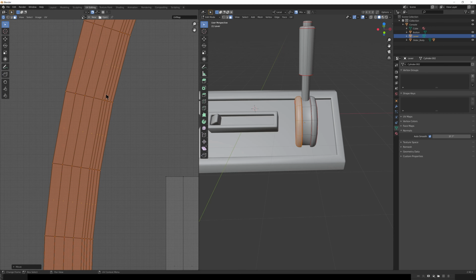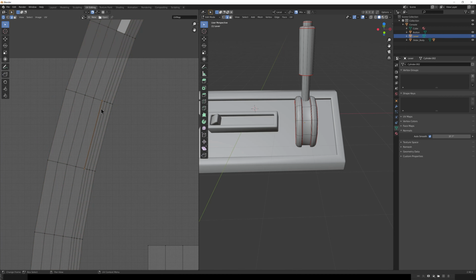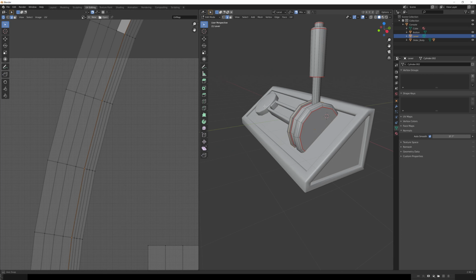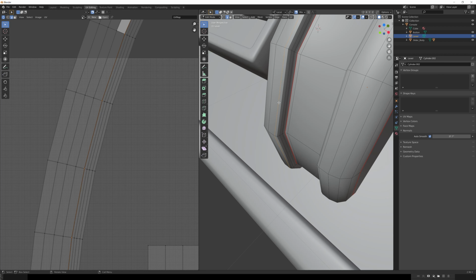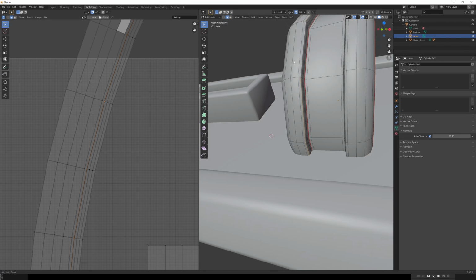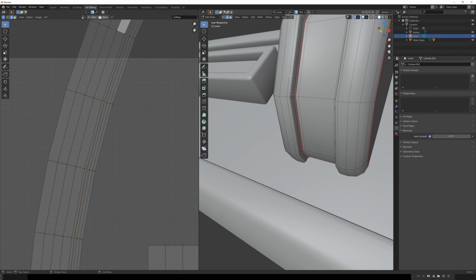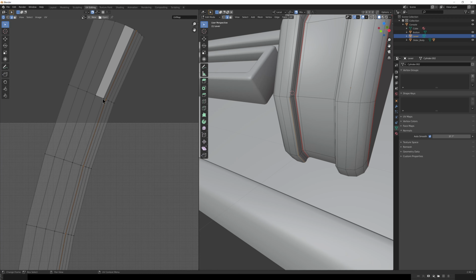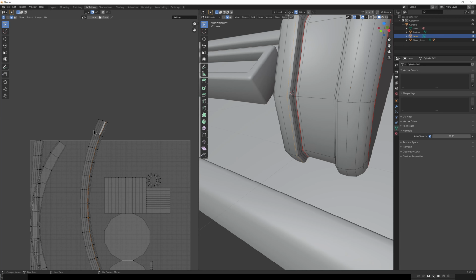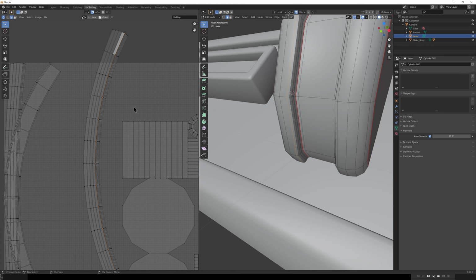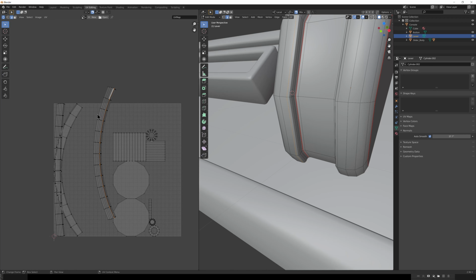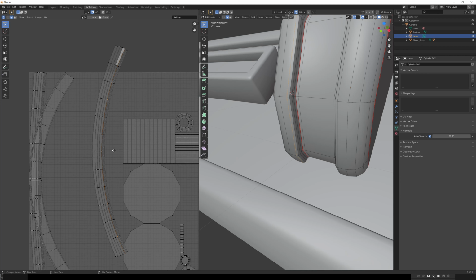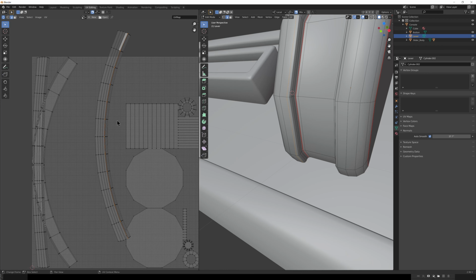If you take a look at how this object is created, you'll notice we have this bevel on one side, right? If we zoom in, you can see it's right there, or actually right there is kind of the trouble piece that's really causing some issues. And if we wanted this to flatten out a bit, we probably could introduce our own cuts somewhere along here, and then we'd have two long pieces. However, the length of this piece is also giving us problems because it's going to try to map the UVs one-to-one. That is, height and width are the same.